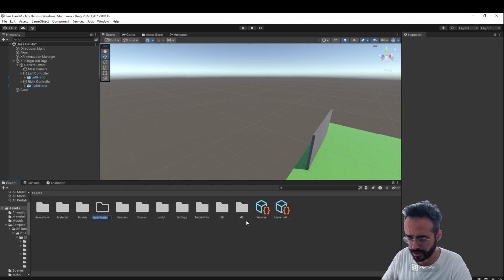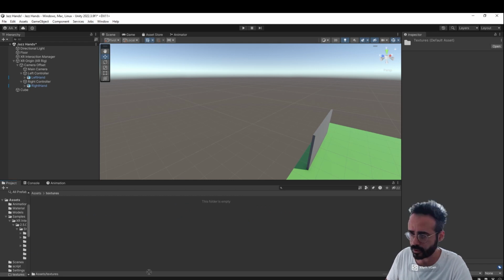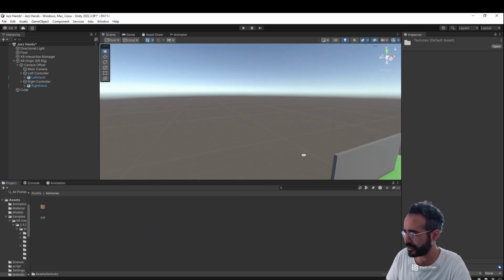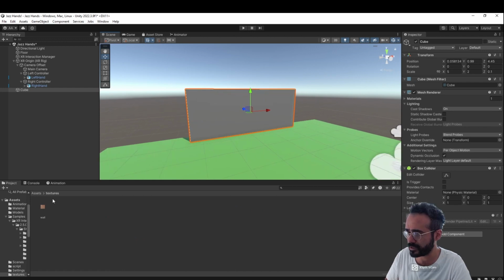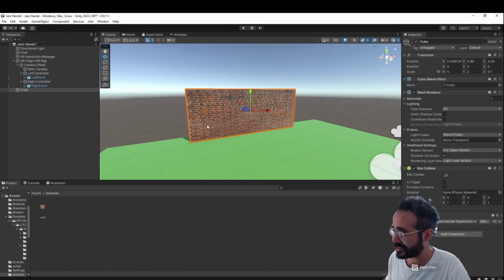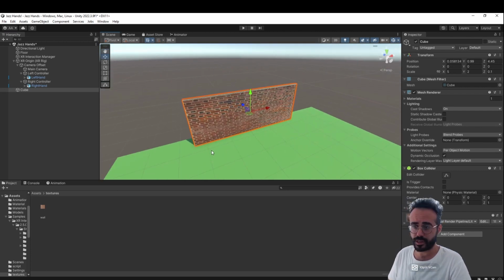I'm not going to teach you how to create textures. For some other project, I have taken some wall texture that I will use. I'm just going to call this texture. Boom. Wall JPG. And now you're really going to see the power of Unity without me having to do much. If you just drag this over here. Boom. That's it. For now, it will look wall-ish.